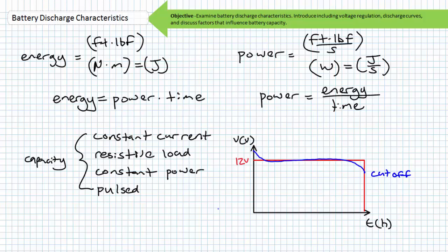The one we'll be talking about today, and the most common specification used, is constant current mode, where a battery is subjected to a load that draws a constant current for a measurable quantity of time until the battery reaches a predetermined cutoff voltage, any further discharge beyond which may permanently damage the battery. The cutoff voltage is essentially when a battery taps out and says, "I yield."